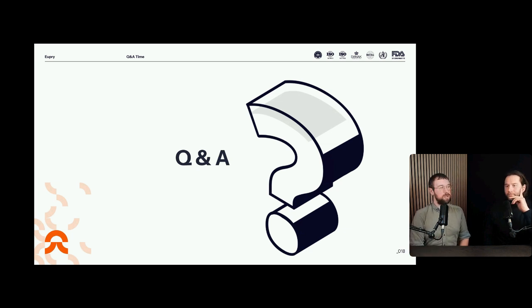Yeah. So sometimes mapping is not a straightforward test where you just conduct the test and get some results. Often it's a bit of iteration, finding out how close to the sides you can actually place products. Because the short answer is you should place sensors where your products are placed. Yeah. It has to follow a realistic operational pattern, right? It doesn't make sense to perform a mapping that does not follow how you actually operate these units.